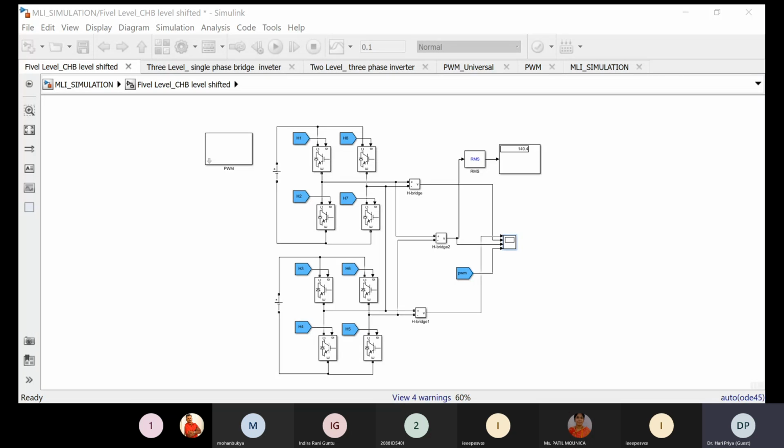These are called separate polarity generators, where the right side is responsible only for generating the levels, and the left side is responsible for generating the voltage polarity. There are multiple types in this, depending on how we use the H-bridge. But since we are focusing majorly on simulating and how to make the PWM applicable for reduced switch count MLI, let me take one of the simplest configurations as an example.